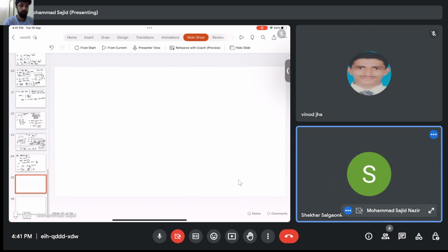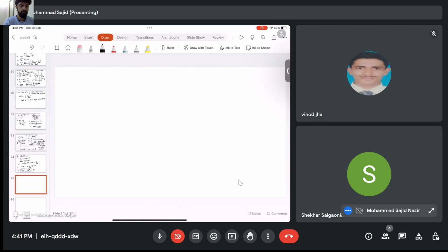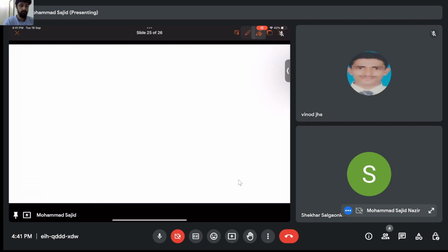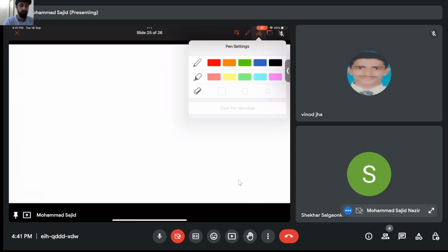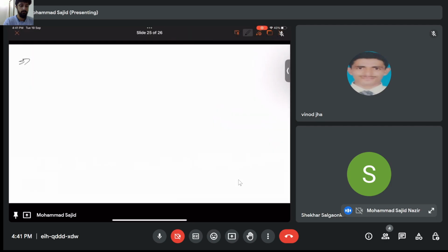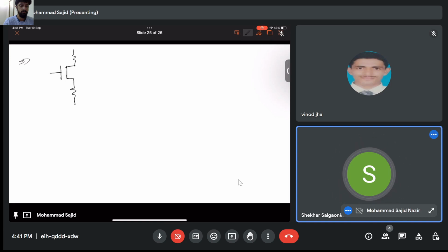As I said earlier, it boils down to KCL and KVL, right? You have the transistor, let's say. Another point is the calculation of the short circuit current and output impedance. For the output impedance, we have to look from the output side, calculate, and see the division of current.